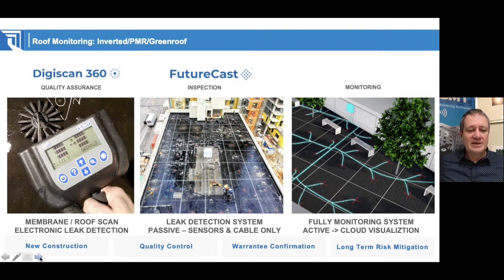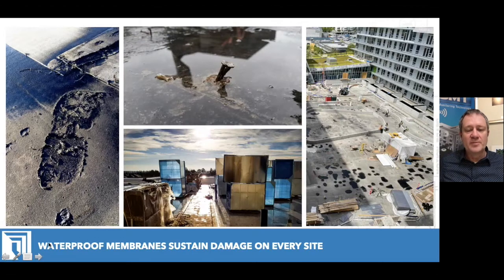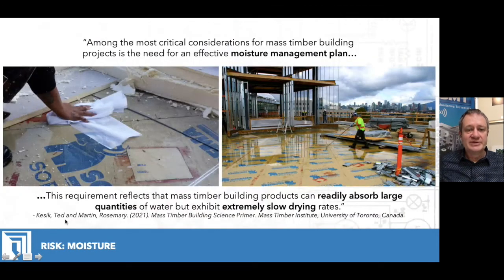Classically, what we've been finding on these types of solutions is that the roof membrane is typically well done by waterproofers, but it's the construction sequencing or damage by others that occurs on the sites, whether it be staging materials, putting forming nails into your project. These are typically what we're finding as damage that happens on every site to horizontal membranes.